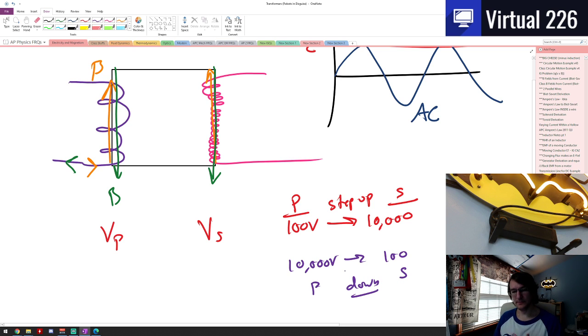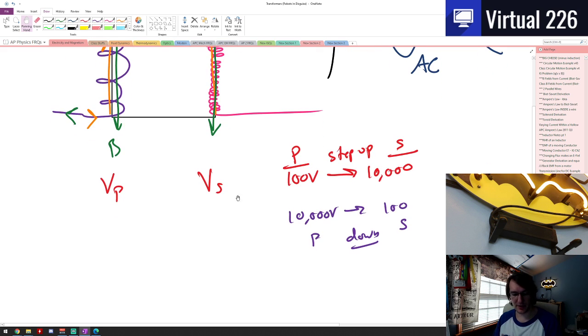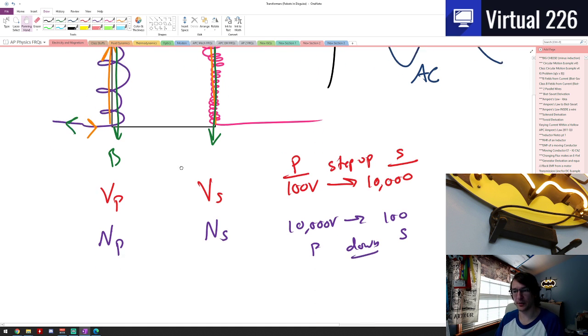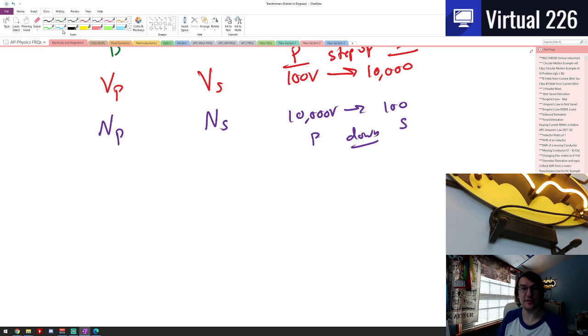Okay? So they're not crazy ideas here, but we've got a primary and secondary coil, and your primary coil has some number of loops, and your secondary coil has some number of loops to it. What's really cool about the actual engineering and design of this is we're able to keep something like 99.9% of the magnetic flux being grabbed by the other coil. So there's very little energy lost in transformers, which is awesome. They're nearly perfect. Well, and for our purposes, they will be perfect.